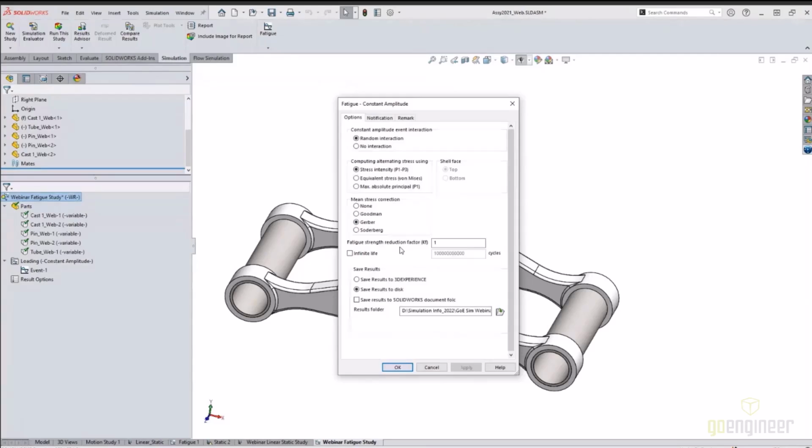And then down below that is the fatigue strength reduction factor. What does that mean? This is where we take into consideration surface conditions, size, load, temperature, reliability, and miscellaneous effect factors. I don't think you can put in 0. Can you do 0? No. It's between 0.1 and 1, but you can't put in 0, and I don't think it goes any higher than 1.